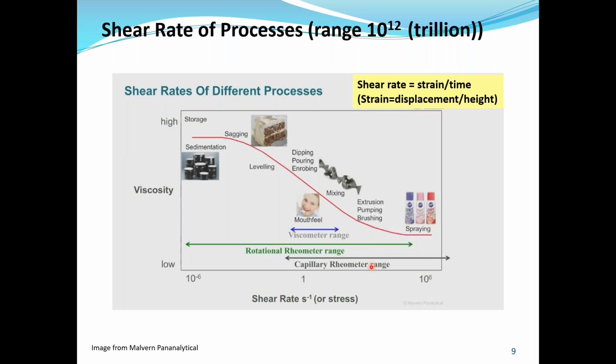And we also provide those services at Rheology Testing Services. We can provide all these studies we routinely do. So capabilities, you really want to have something that can go down to a very low shear rate, at least down to 1/1000th of a reciprocal second, and also go up to very high shear rates. So again, the rotational rheometer should meet your needs pretty well.